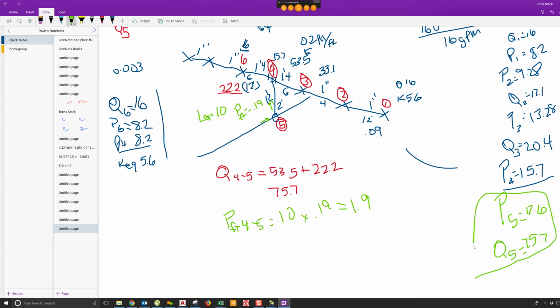Do you guys see how that works? Yes, no, maybe? Cool. That's basically the hand calcs that you're going to do in a NICET Level 3 exam. You run through those different scenarios where you've got to figure out what the flow is based on your area of coverage and your density, and then you know your K factor, so you figure out what your minimum starting pressure is. Then you just figure out friction loss through the pipes, add equivalent length for fittings if you need to. When you get to a junction point, so like we had, oh, I lost my mouse again.